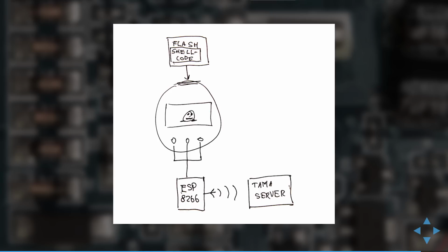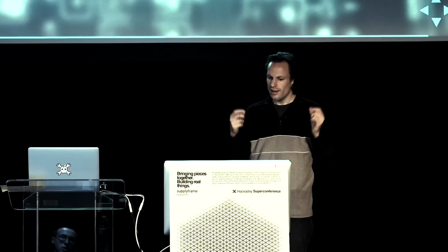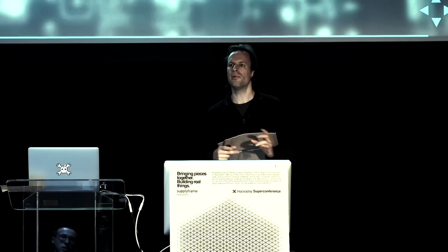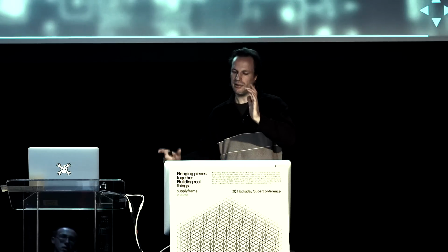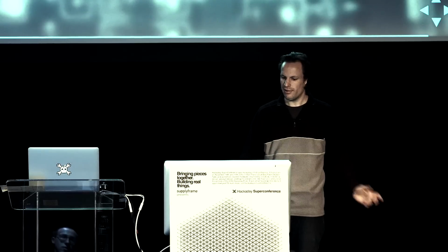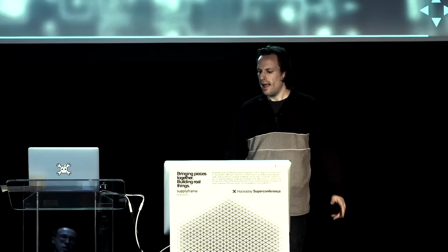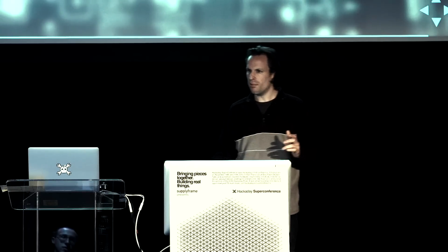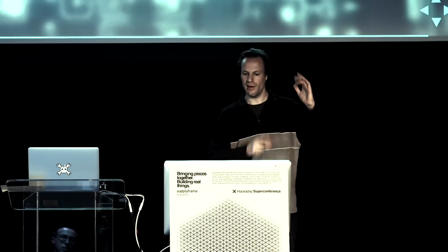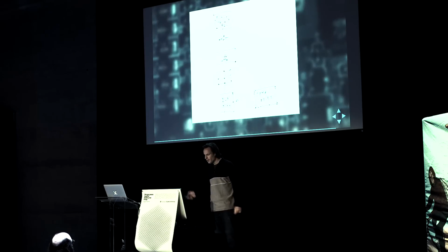In place of the figurine, I have my little flash chip with the shellcode in there, and a little piece of 6502 code that reads the button inputs, processes it as a sort of SPI input, and then takes the data and sends it to the video RAM. The buttons themselves are connected to an ESP8266 module. That's one of those chips that can do Wi-Fi. The ESP8266 will initially twiddle with the buttons to get into the game that starts up the 6502 code, and will then just get images from the Tama server to display on the little LCD.